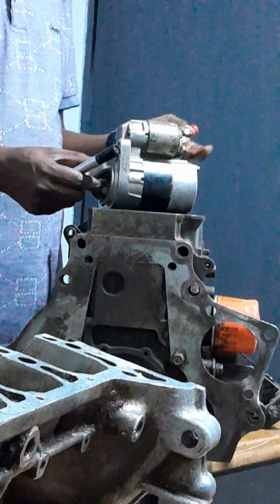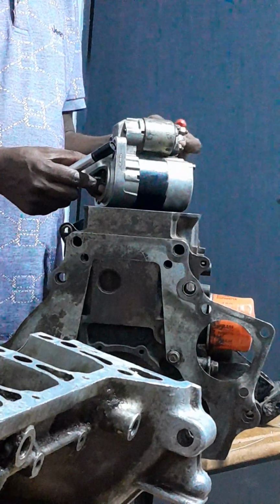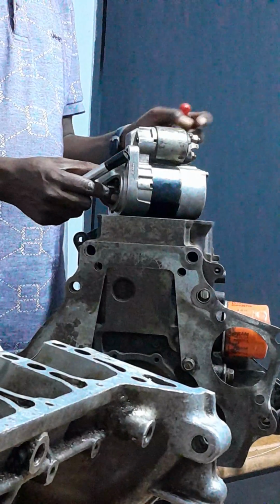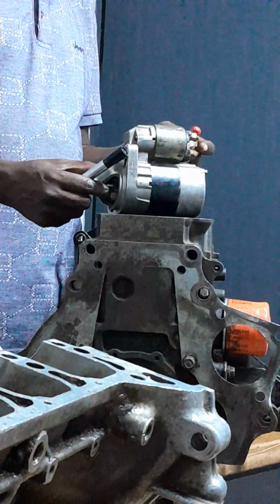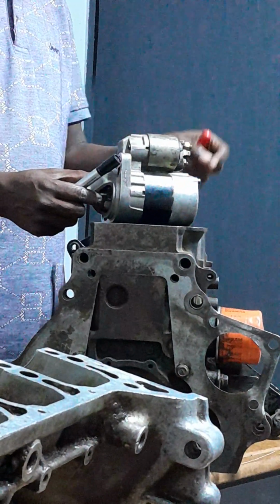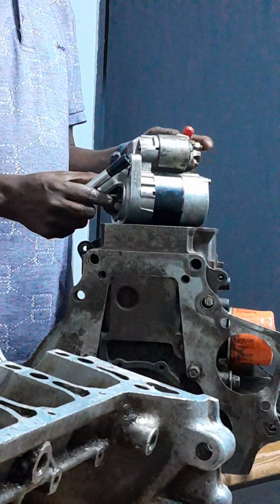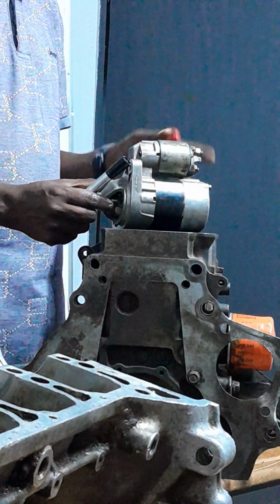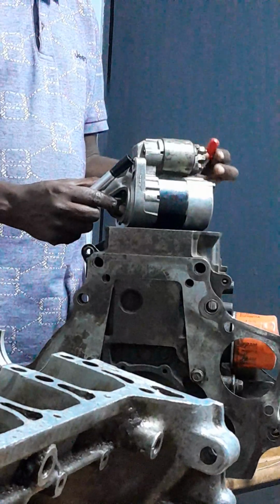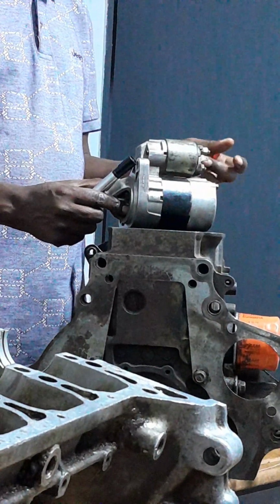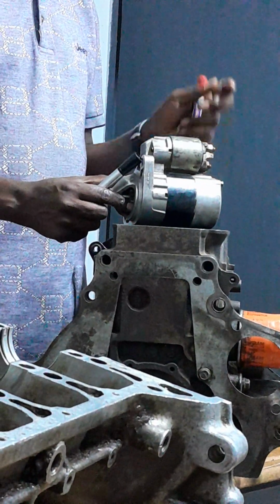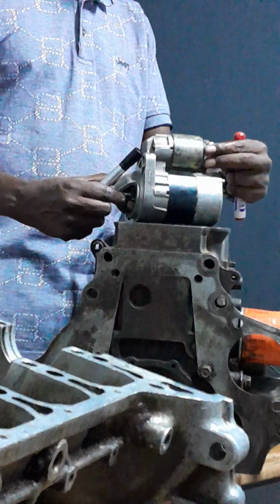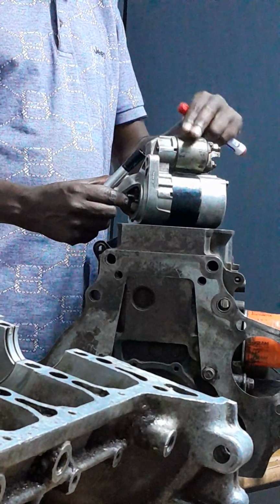Then at the other end of the solenoid, we've got a pair of heavy-duty contacts, which when closed will then connect the battery directly to the motor. So the heavy-duty current to the tune of 150 amps is connected by the heavy-duty contacts that are at the back of the solenoid. For that to happen, the driver will have to supply the solenoid windings with power, and